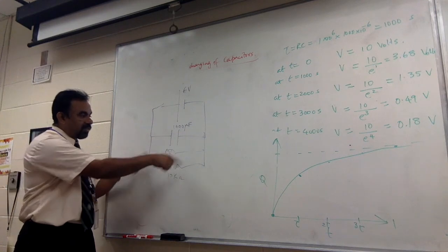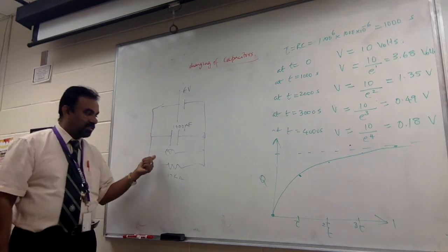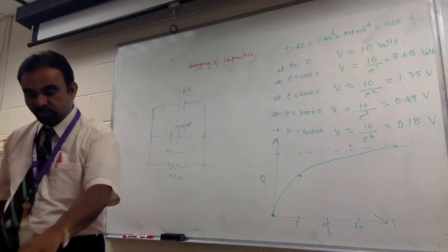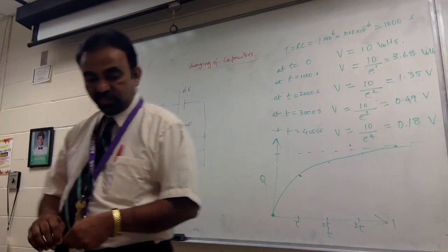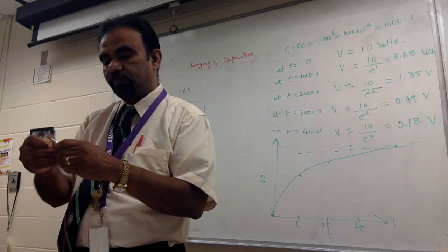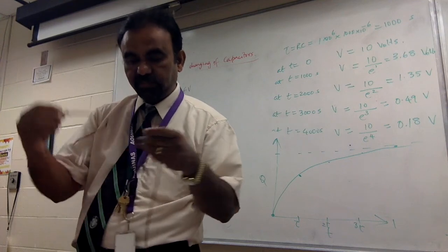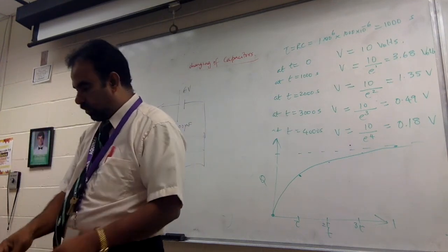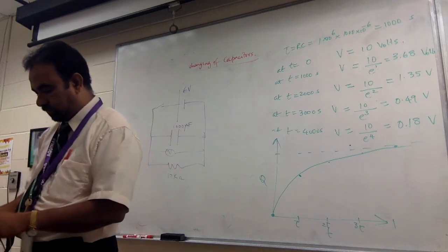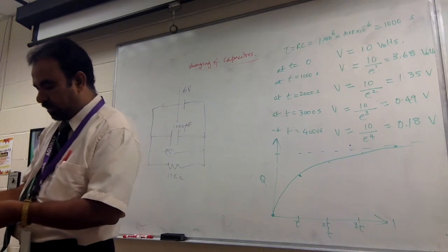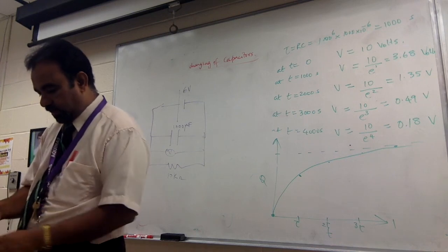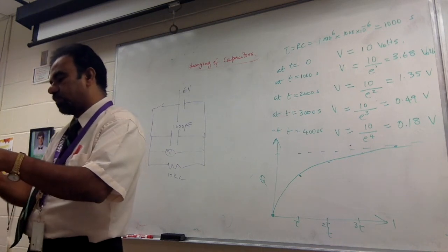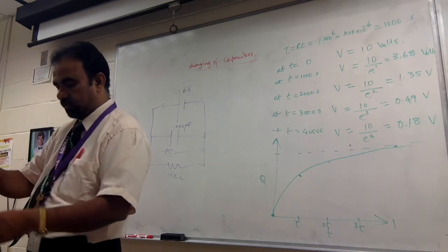Now what is to be connected across the capacitor are two things, the voltmeter and the 10 kilo ohms. I need to connect the 10 kilo ohms. So I connect it like that, to this. Doesn't matter, any polarity is good. So the 10 kilo ohms is connected across. That's done.